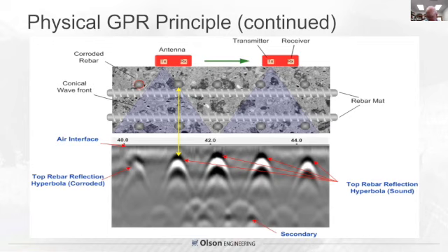So having said that, you can see at the left, that is not as clear a signal. The signals are much clearer. The center of this hyperbolic reflection is the black spots. That's the top of the rebar. And you can get depth of cover by calibrating it for the velocities of the material. And you can get that from the shape of the hyperbolic fitting of these curves from single rebars, or if you know the thickness and see a good backside, you can do it that way as well.